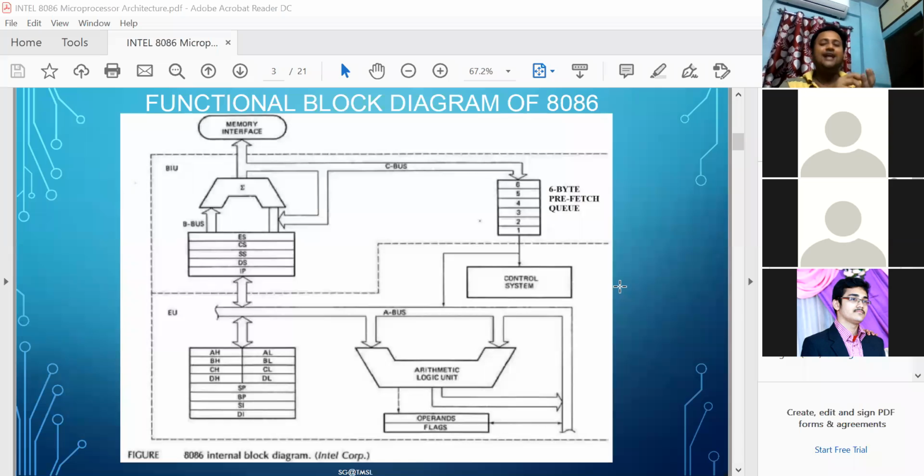Because within that code segment, which is initialized from 2000 to 2FFF, every instruction will be written in this position. No instruction will be written in 3000 or 4000. If you want to store any data, and the data segment has been initialized at the 9000 memory location, then you always need to use the 9000 memory location for data storage. You can't use 5000 or 6000 for that.